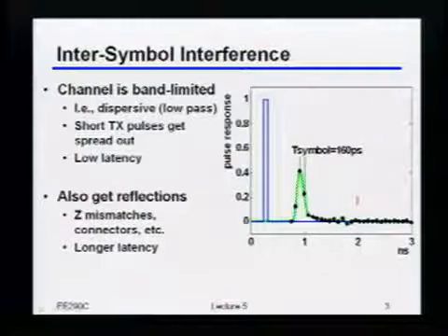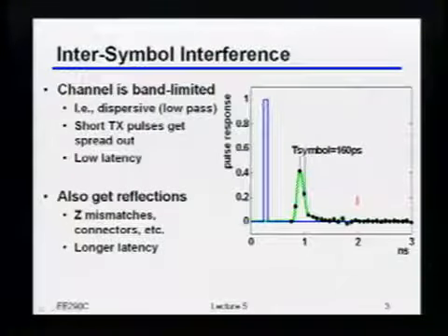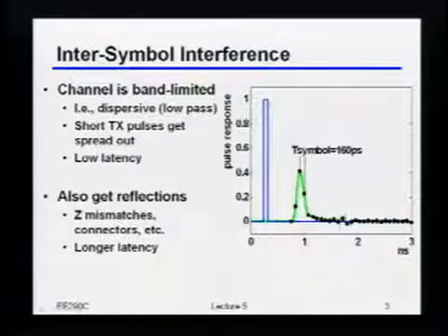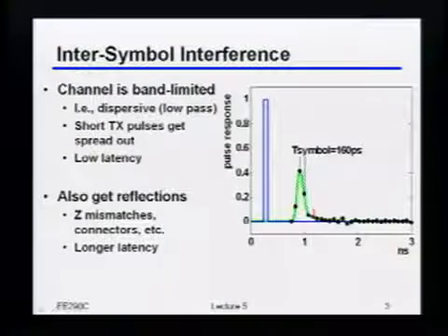Right? Those are basically reflections that took additional time to propagate down the channel and then finally show up at the receiver. Okay, so a fairly common type of link response here would be something where there's this dispersive, close-in kind of response. And then sometime later, these reflections come in and cause a little bit of additional ripple or weird-looking behavior there. Okay?